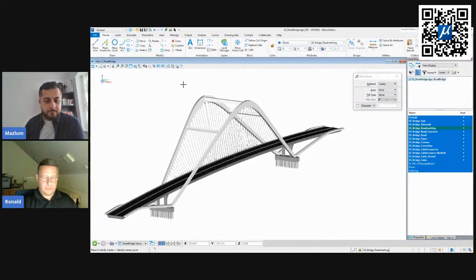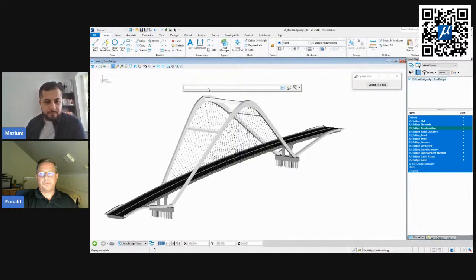If you look at my screen very carefully, I just have to type a backslash before to tell MicroStation, hey, that's an AutoCAD shortcut. So \C would open the place circle, and I guess \R is something like redraw the view, and so on. So this is based on original AutoCAD files and AutoCAD shortcuts.